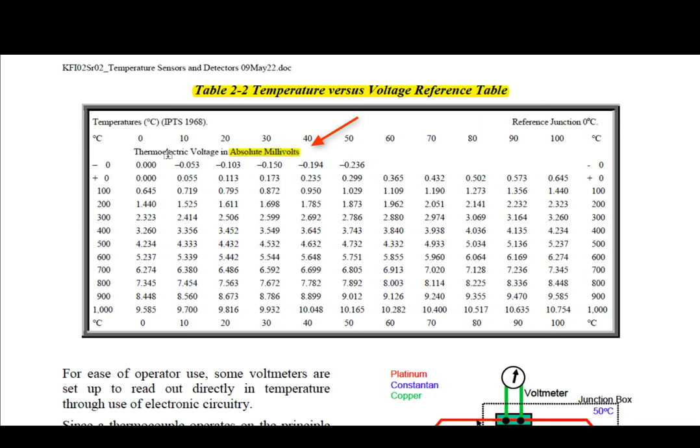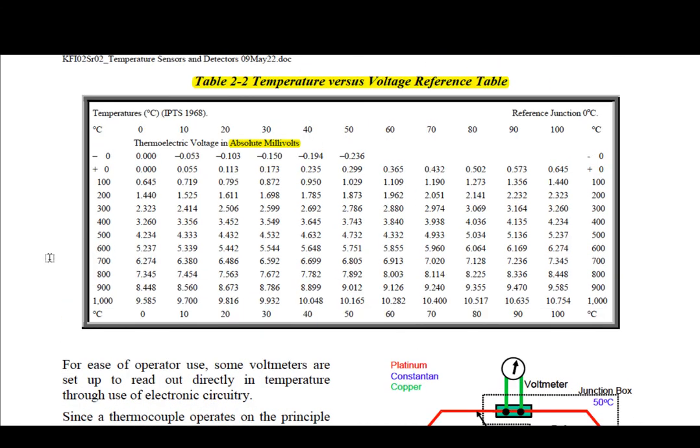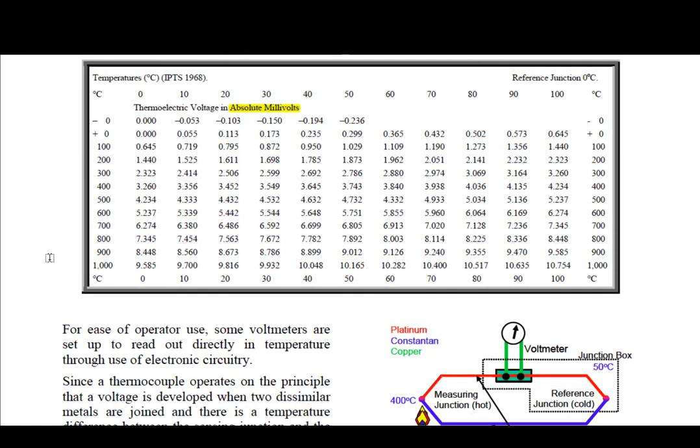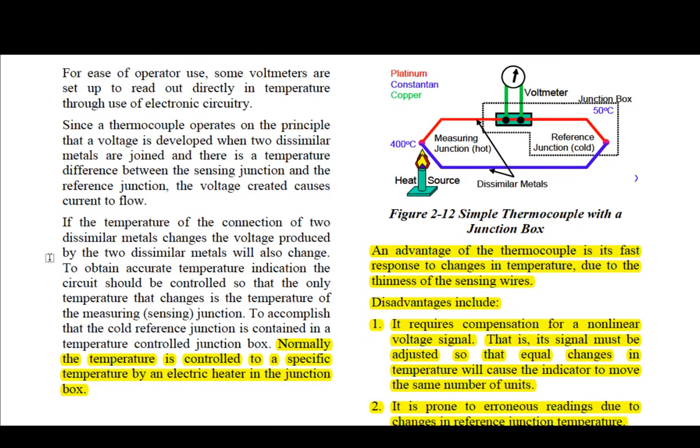And so you remember, you have to have a large differential in your millivolts so your equipment can make the detection as to what the temperature is. If the millivolt number is very, very small in comparison to the temperature change of the dissimilar metals, then we'd have to put some kind of gain, operational amplifiers, things like that, to increase the value so that our sensing equipment can actually read it.